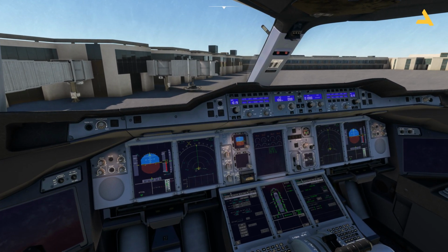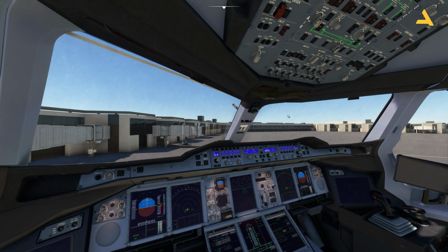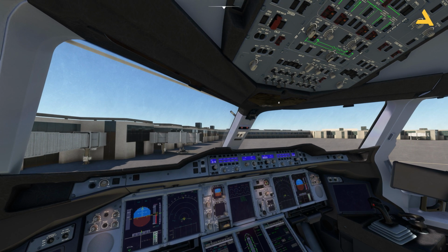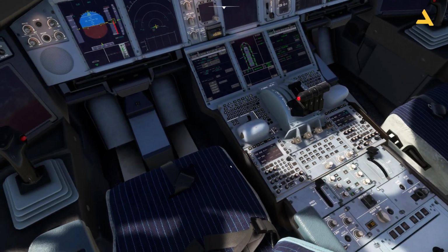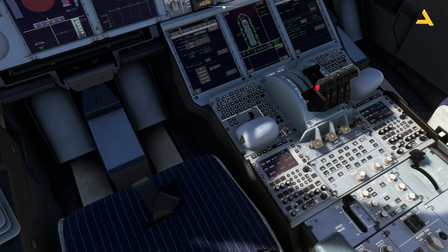Now the altitude will be 38,000 feet. And I can turn on the flight director and the speed in the manage mode. So just like the Airbus, you can have the manage mode for the heading, for the speed, and for the altitude. And when you see all these three dashes. So now the APU is available. As you can see, it's coming over here. You can also see the progress of the APU.